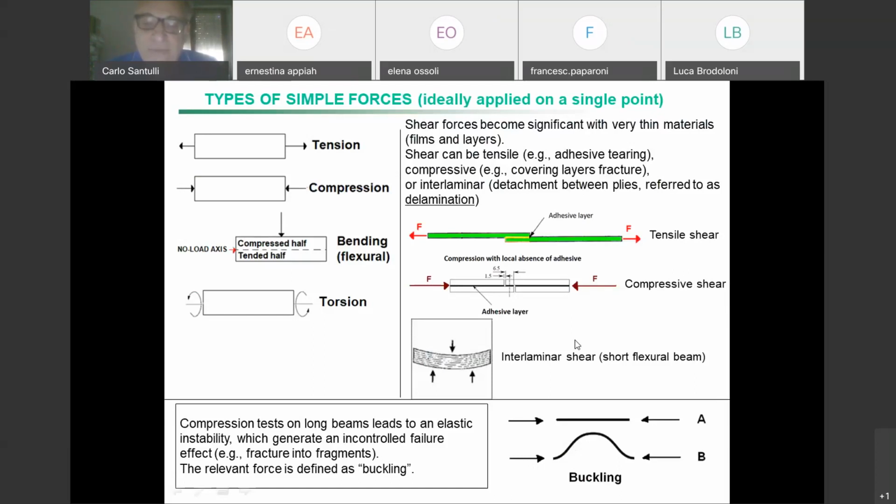If the area is quite small, they tend to be bent. It happens with wood laminates, and they tend to be delaminated. They tend to fall down, to separate from each other. You may have found this in furniture, especially for example in the kitchen. It's quite typical that they tend to detach. Also by the effect of water acting on the glue, which makes it detach.